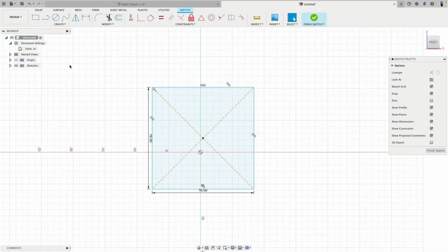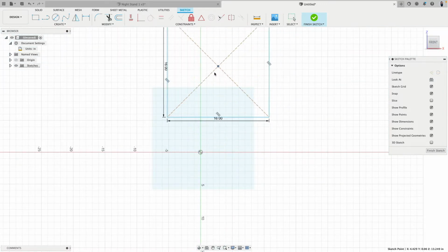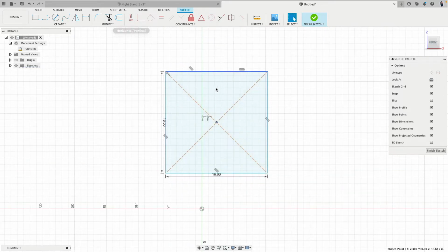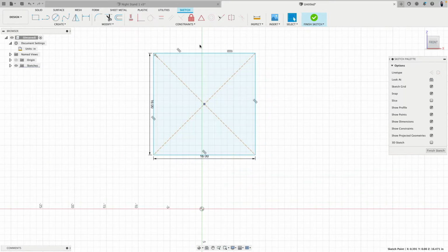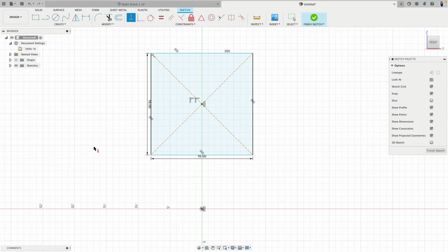We have to zoom out a little bit more. Then this midpoint, I move a little bit up and move this somewhat over the y-axis. And then I click vertical constraint and align this. There, perfect, cool.